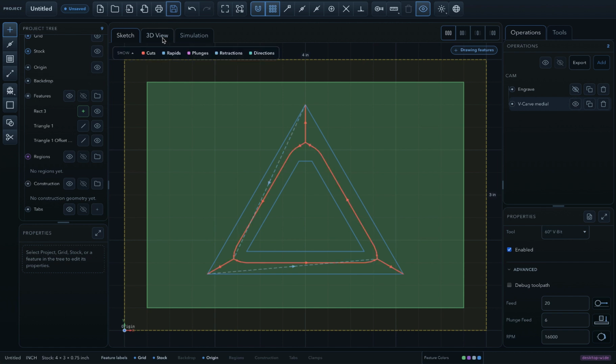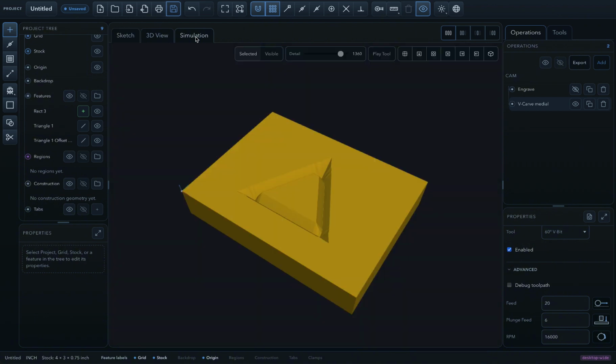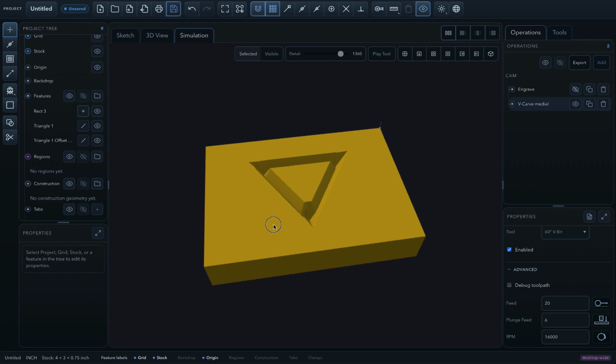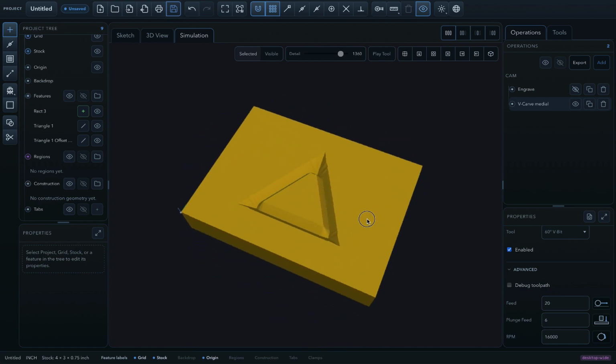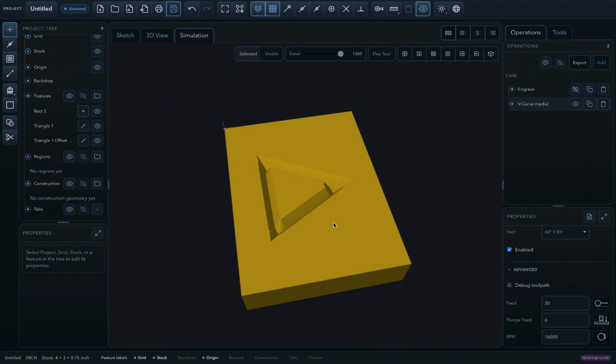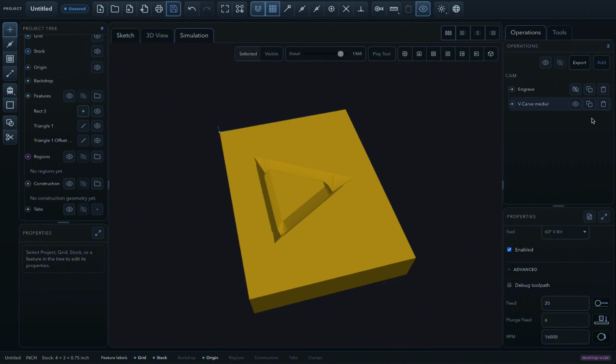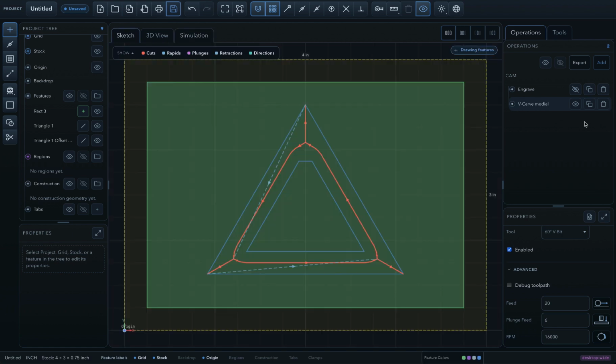Lines also support two other useful CAM workflows. A closed line can be selected for a V-carve operation, which cuts its enclosed geometry with a V-bit. A circular line can provide the center information for a drilling operation. Again, use the mode deliberately. A line circle describes a path or center, while a subtractive feature describes actual removed cylindrical material.